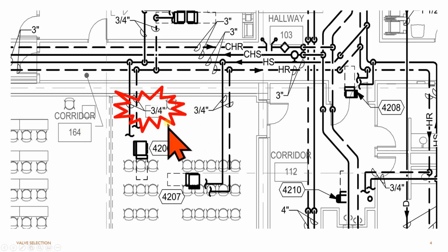my bad, 3/4. So let's take another example. Here we have a hot water pipeline, and this is a chilled water pipeline. This is 3/4 and this is 3/4 going to some other unit. So you have to consider the last end size which they have given.